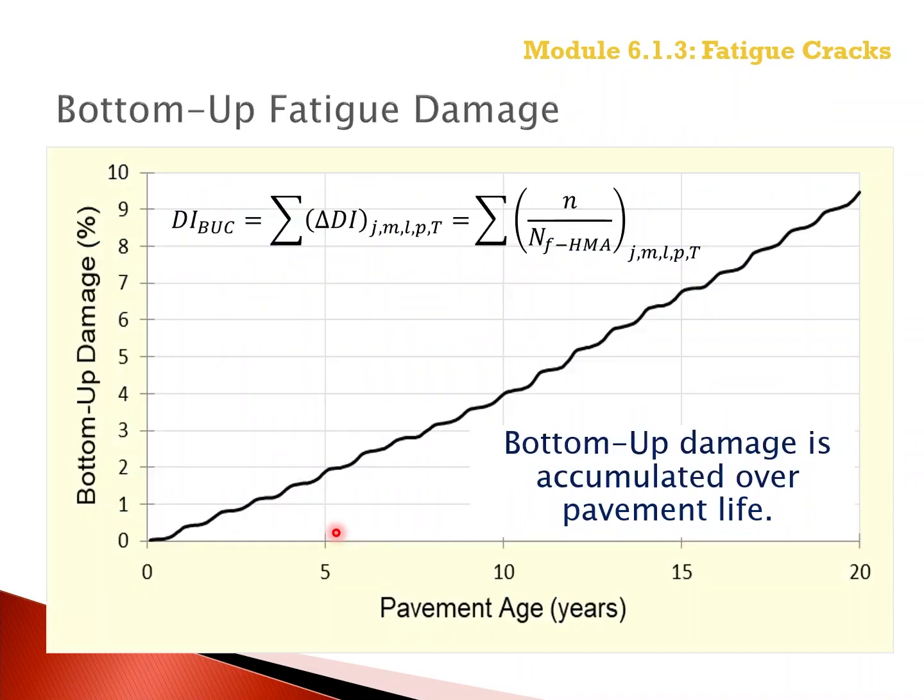In summary, the fatigue damage is calculated throughout the design period considering the variables listed and noted on the previous slide. The fatigue damage for top-down longitudinal cracks, or the fatigue damage for the bottom-up longitudinal and alligator fatigue cracks, are listed in the output report, which is graphically illustrated in the figure displayed on the slide.